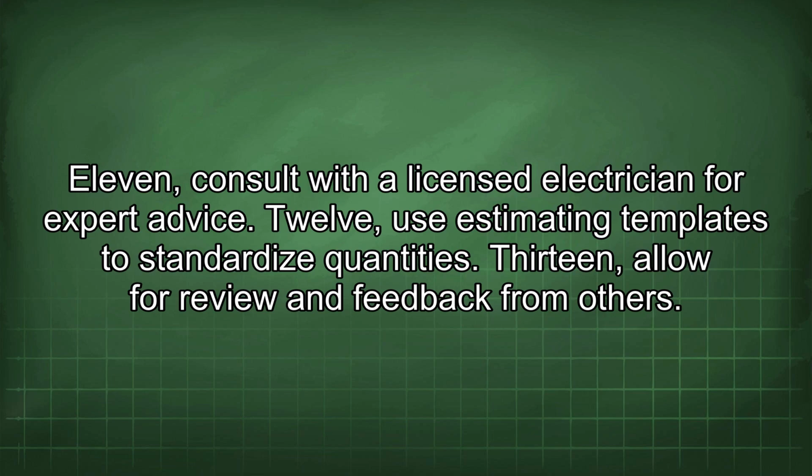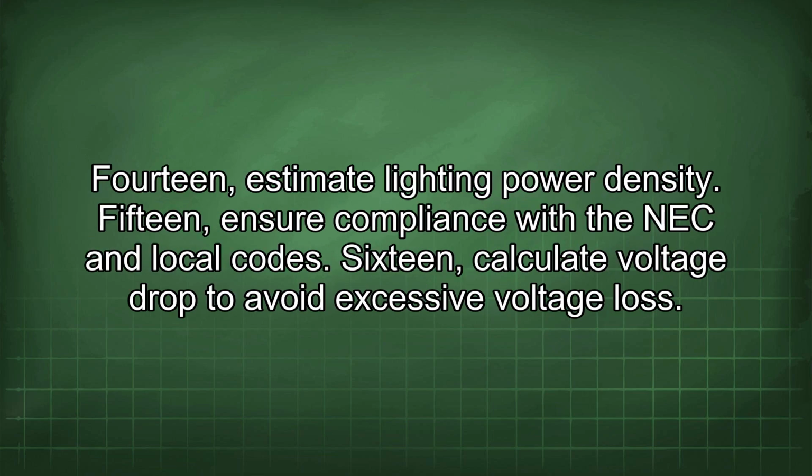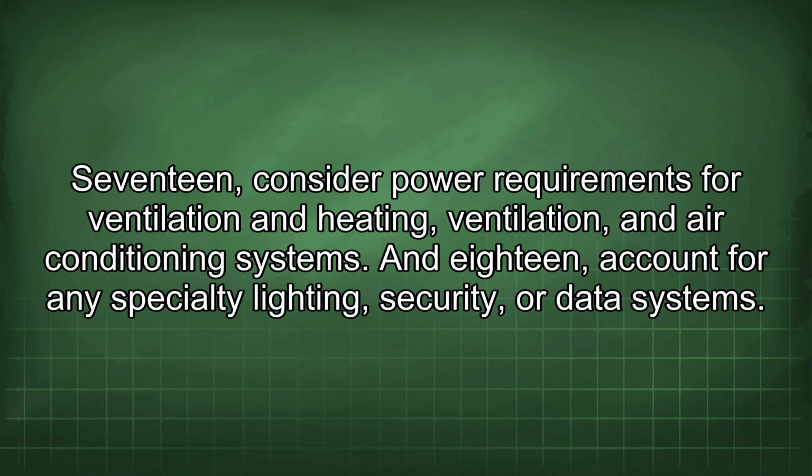13. Allow for review and feedback from others. 14. Estimate lighting power density. 15. Ensure compliance with the NEC and local codes. 16. Calculate voltage drop to avoid excessive voltage loss. 17. Consider power requirements for ventilation and heating, ventilation and air conditioning systems. And 18. Account for any specialty lighting, security, or data systems.